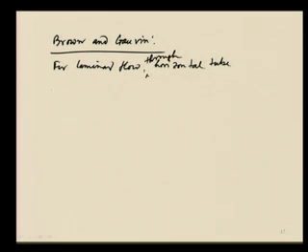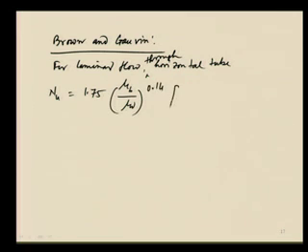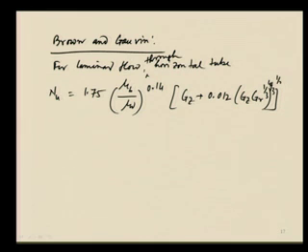Under that situation, Nusselt equals 1.75 times mu b by mu w to the power 0.14 into Gz plus 0.012 into Gz into Gr to the power 1/3, whole to the power 4/3, and then whole to the power 1/3 again. Here Gz is the Graetz number.